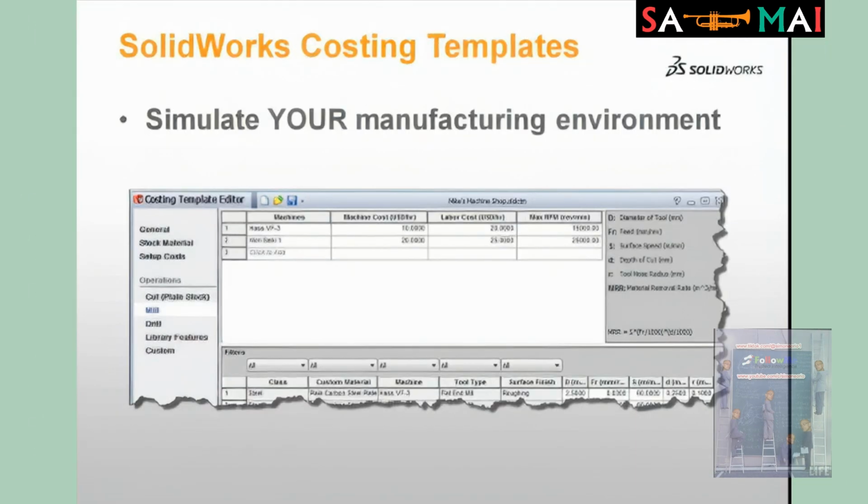And the machining one, you can see here from the image, it's very, very similar to the sheet metal one, where you can put in the tool diameter, the feed and the speed, the tool depth that you want to go through, and your machines on each one to set up. And you set that up one time, and then you don't have to change it unless your inside part or your inside environment's changing. Then you can update that as needed.